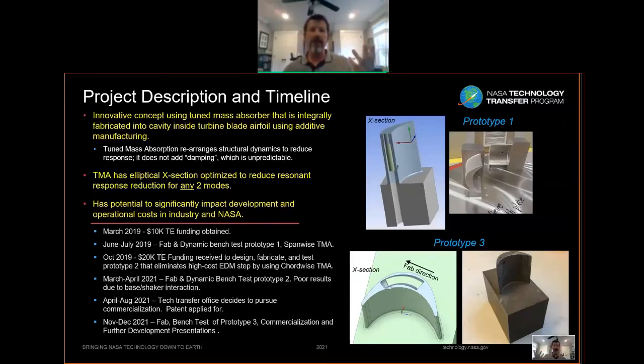So additive manufacturing is direct metal laser sintering, and it lays down a powder, moves a laser over it, and actually melts that powder into the form that you're building up. So you have to blow out the powder that was left in your cavity. So you just blow it through those holes, which is quite easy.